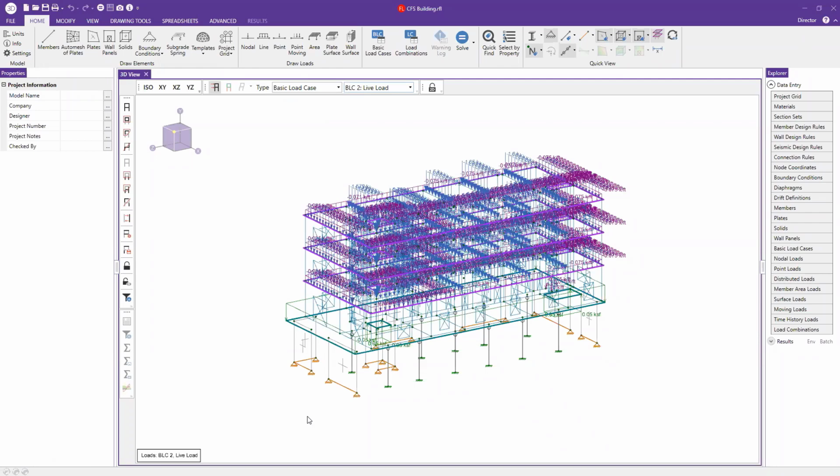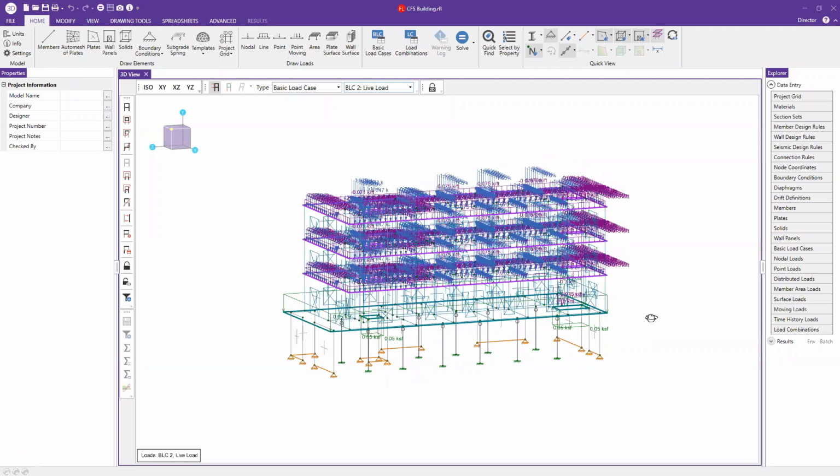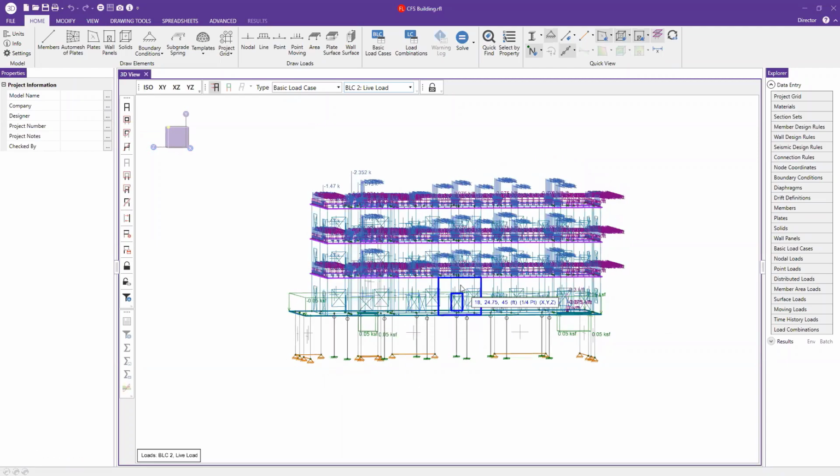When I'm building a model, I'm thinking through the elements that come across that are contributing in that area. What I also added on the base of my model, I just propped this up with pinned columns. So they're just along for the ride, but I want the bottom of the base of my model to really be those concrete shear walls that I have. And some of these are riding all the way to the top for my elevator shaft. But mostly the concrete sections here are just going to be that level. And then above that is each individual panelized wall.